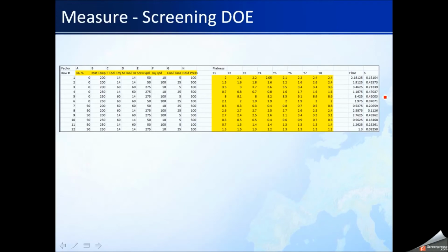And here is the pattern. So there's the pattern. Key point about the efficiency here, as I mentioned, we have 8 variables, 8 settings. We are only going to do 12 tests, 12 setups, although obviously we are repeating, we are collecting a sample multiple times for that setup, but we're only going to set the machine up in 12 different ways.